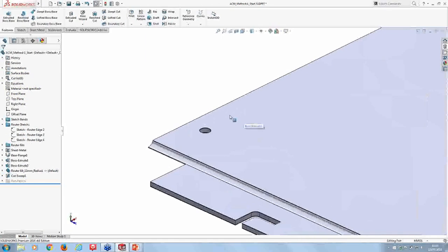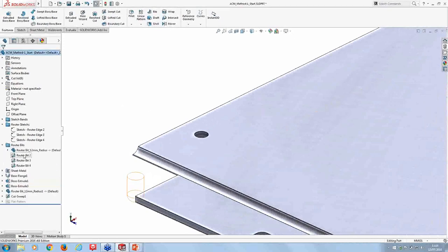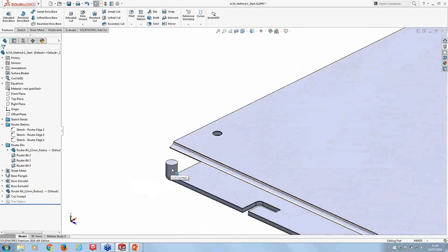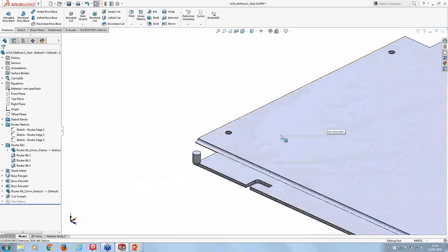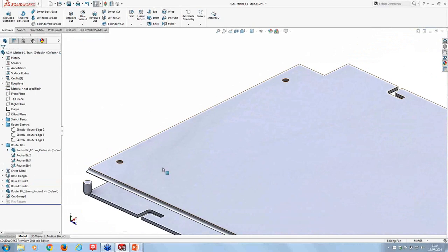Obviously, as I said, this doesn't have to be the method you use. It could just be a simple extruded cut. Just for the purpose of this, though, I'm going to stick to the same method, and I've already put in some other bits. I can only use the bit once for a profile, and if it was a circular profile I could come around in a whole loop. Actually, when I was putting this webcast together, I did find for this particular operation I had to run it as 4 separate cuts. So let's just turn on the next profile and do the same process again.